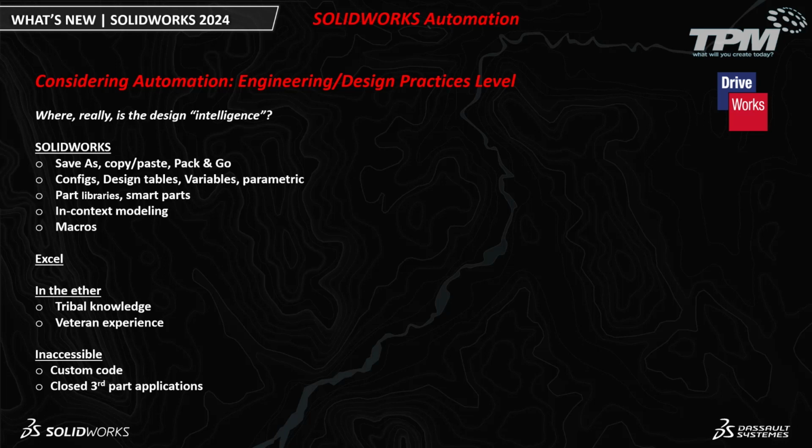Top-down or in-context modeling is a savvy technique that builds relationships across an assembly. This is a nice time saver and error prevention technique because design elements can enjoy a one-to-many relationship that avoids repetitive data throughout the model data set. The one inherently limiting downside of these relationships, however, is that they are explicit dependencies that are established on presumptions or knowledge that may not be suitable for recycling later. Top-down models can quickly implode if the dependencies are not honored, which also yields a scenario in which confusion can outweigh the intended benefits.